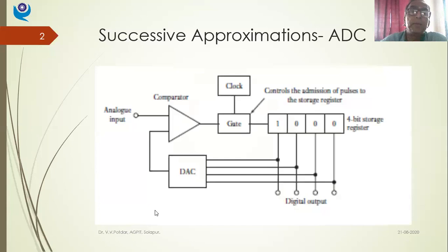I'll try to explain to you. Now, as you can see in the diagram, you have one operational amplifier here, which is acting as a comparator. What it does is compare two signals, my set signal and my generated signal, and after comparison, it gives out some signal. So the op-amp as a comparator is used here, and as you can see here, there is one logic gate. In this case, it will be an OR gate.